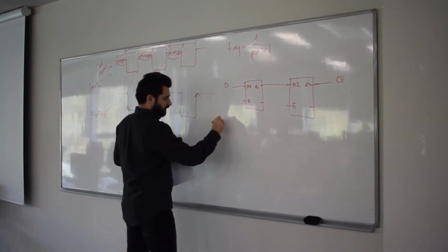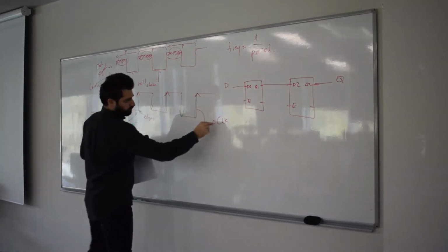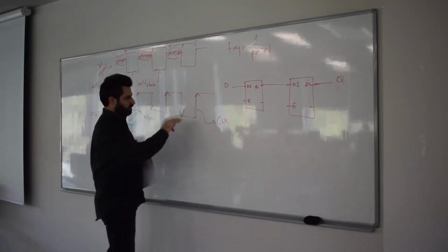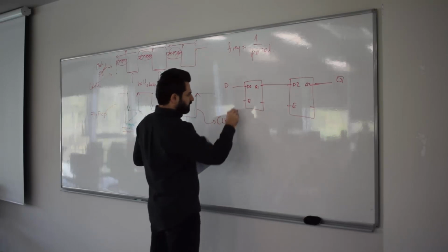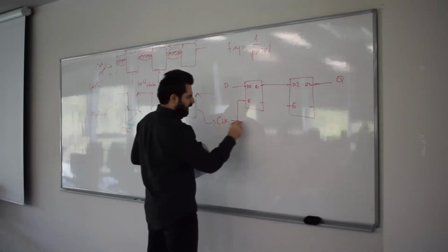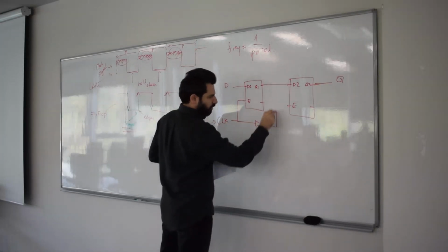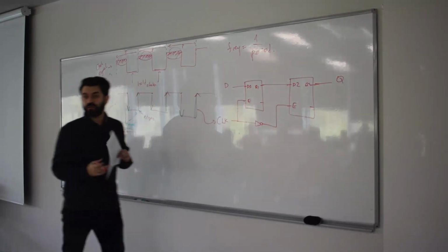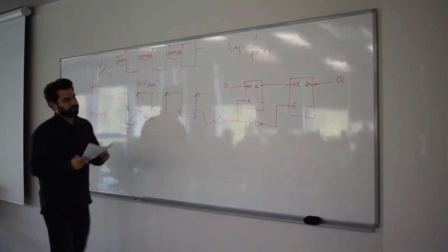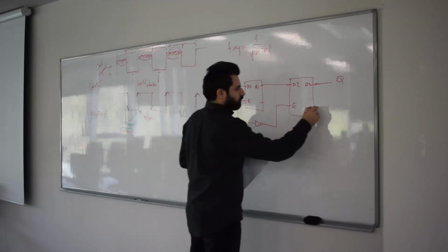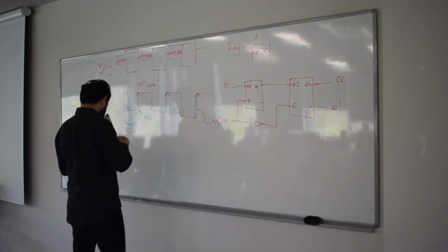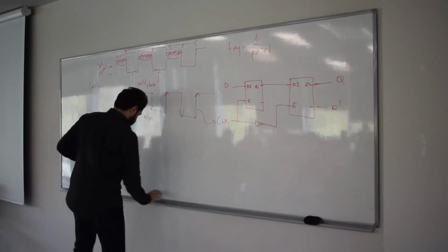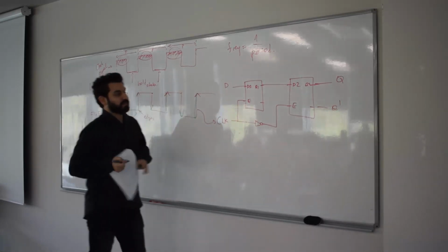And I have a clock signal, this one, going into enable, as you can see, it's a periodic waveform, and the negated or inverted version going to the other latch. Okay? And of course, this is going to be our Q prime. Okay, so this, which I claim would be operating as a flip-flop.